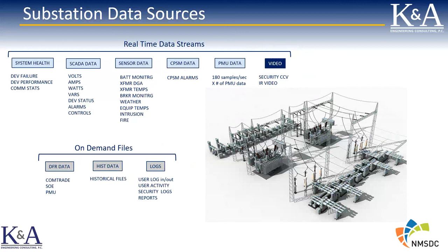We can cross-check instrument transformers one against the other, and also monitor the condition of the protection devices and the network switches used to build the station network. So if there's a problem with communications related to protection, all that is flagged and alarmed.